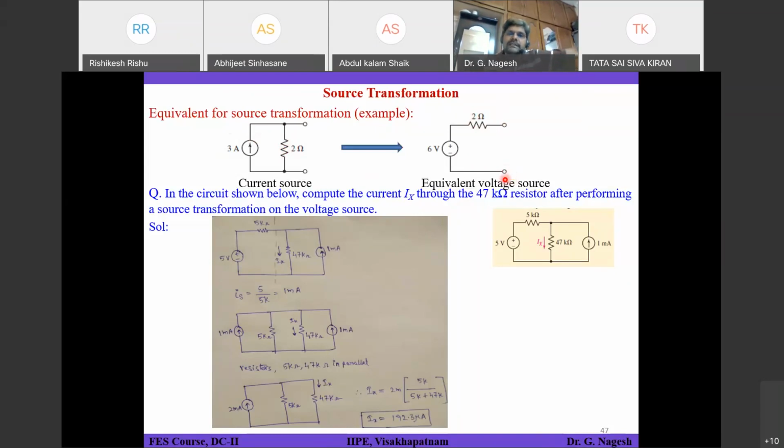That means if you connect a load resistance RL of different values, let's say RL equals 50 ohms, in both circuits and find out the current in both cases, then if you have only 2 ohms here and 2 ohms here, your solution will be correct. Otherwise, if you have 2 here and 10 ohms here, it is not going to be correct. They analyzed by connecting an RL load and observed that when RS is equal to RP, both circuits are identical.